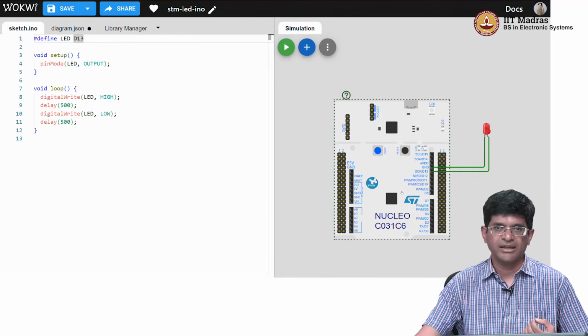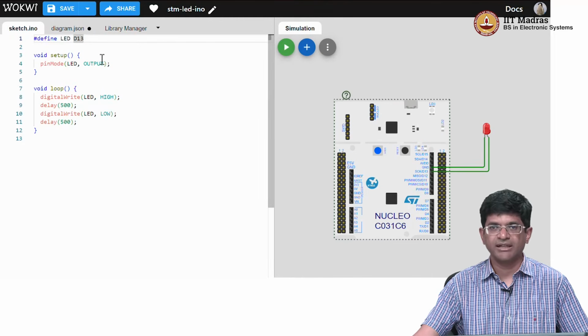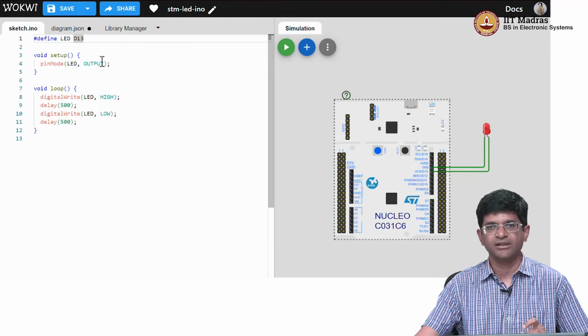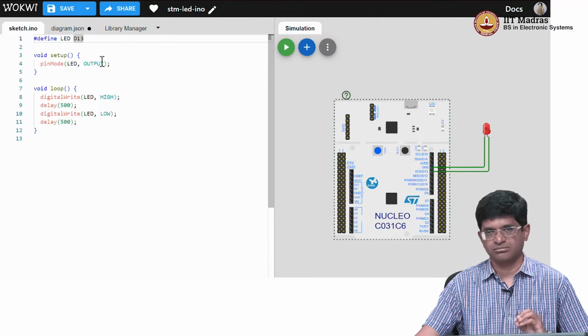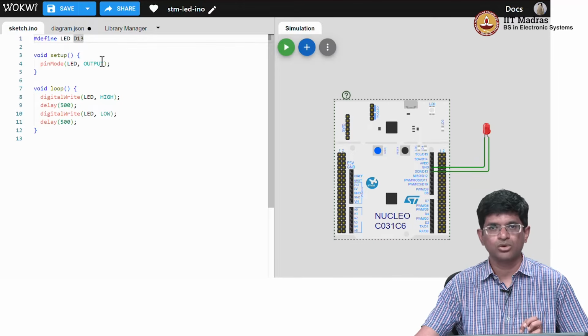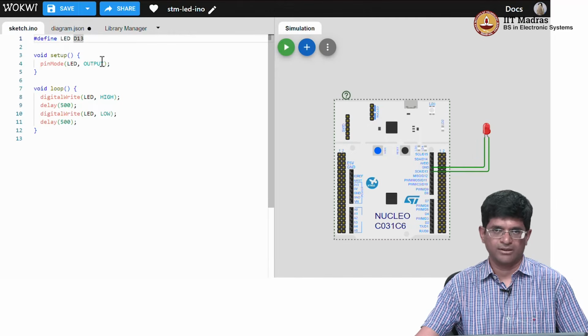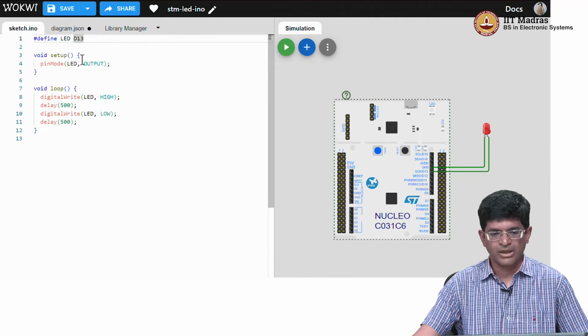And by specifying this D13, we are actually able to abstract away a lot of the details and say that if a particular signal is given, I need to go in there and set a particular bit in a register, which in turn will cause a particular pin to go to the value 1, logical value 1.